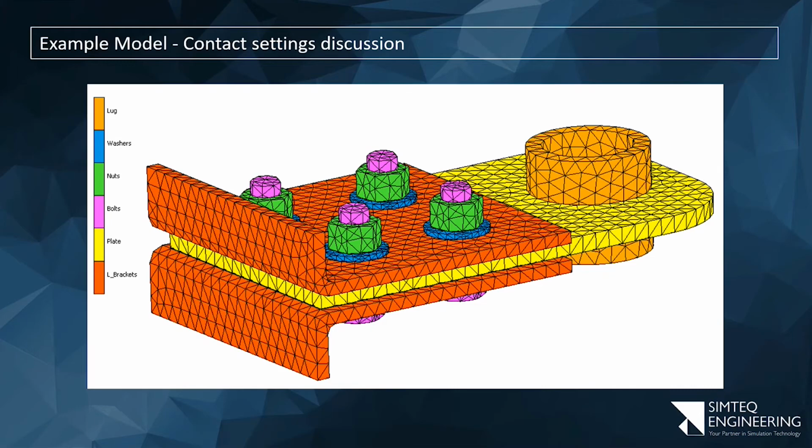Okay, the last one that we haven't discussed was simply the yellow part of the L bracket, so the center plate. And there's nothing special we need there other than, again, stress-free projection, which I almost always use. I don't want an initial interference slip there. And I need to specify friction between these two if I want to run include friction effectively. If I don't include friction, the model will actually not run because it's effectively as if I then have Teflon or grease between the yellow and the L bracket.